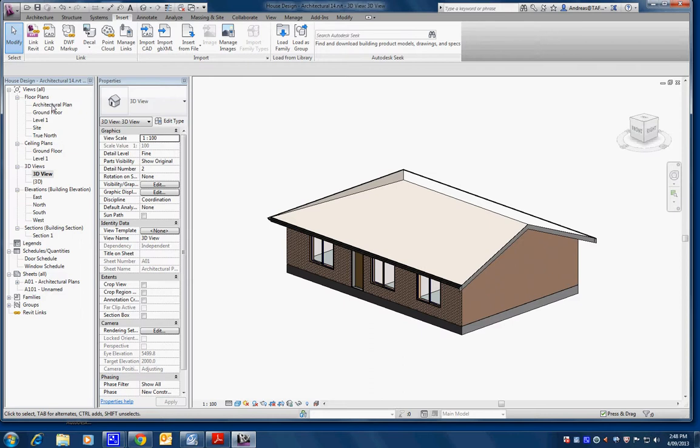If it's a Revit file and you externally reference it in a Revit file, it's called a Revit link. So if we had a Revit link in here and we wanted to export this Revit file as a DWG file, it won't merge the two together. It will still keep that link as a DWG file, but externally reference it into a new DWG file. So it converts links into external references, which are basically DWGs anyway. But you end up with two files, not one.